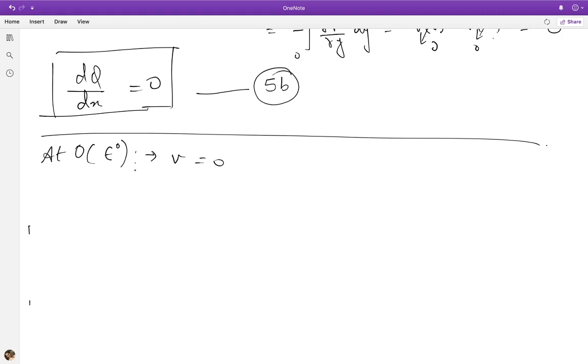And from this we of course get that u is fully developed, which then from the momentum equation will simply tell us that d square u0 by dy squared equals -1, after recognizing that the pressure perturbations don't exist at this order. Even if we had included functions basically g0 and f0, we would find them to be 0. And so the solution to this problem, along with the boundary conditions, is as follows.